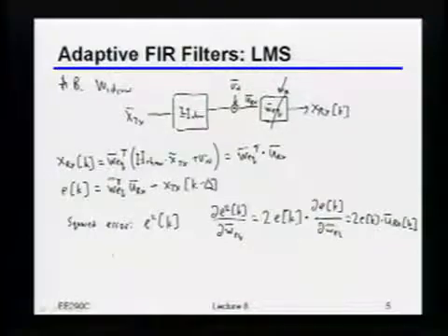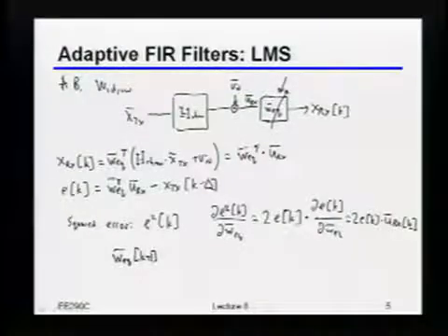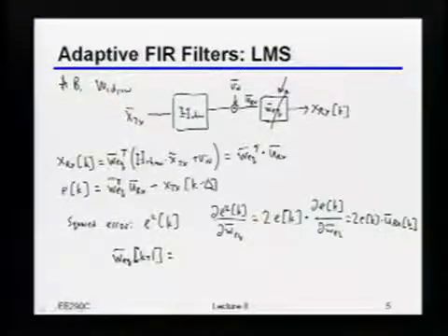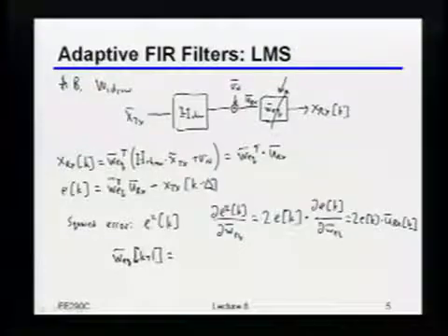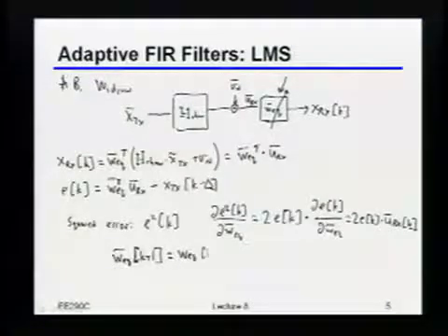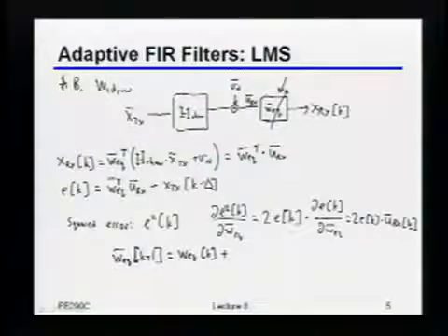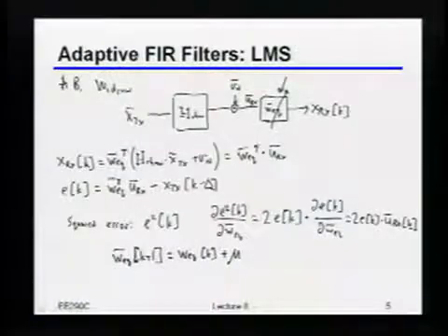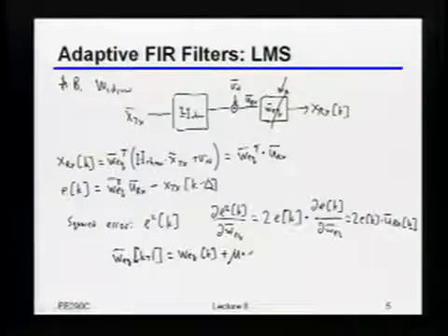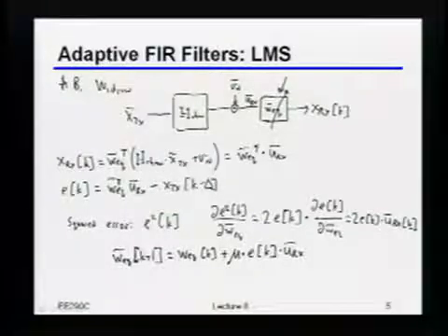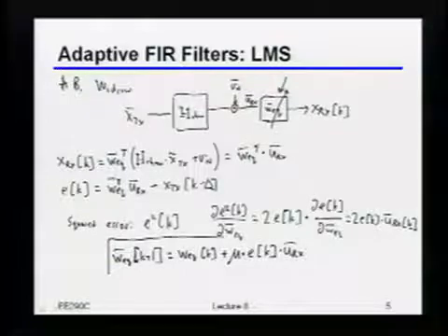Okay, so to just write that out, these are usually referred to as update equations. So basically, if you know what the gradient is at one particular sample, then your new value for the equalizer should just be whatever the old value was plus wherever the gradient is pointing you. Okay? And so I'm just going to introduce one other parameter here, which is called mu. That's just normalizing the step that you take. But basically, I'm going to do that times essentially the gradient, which of course is just e of k times u_rx. Okay? So that's really how you actually will build this thing.